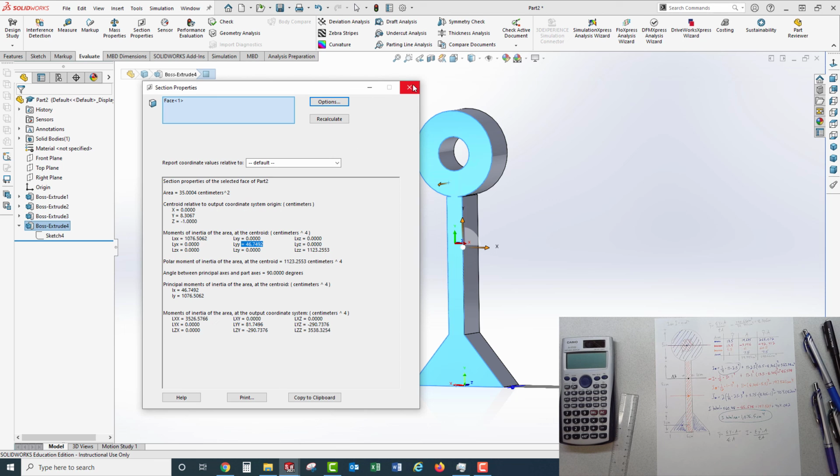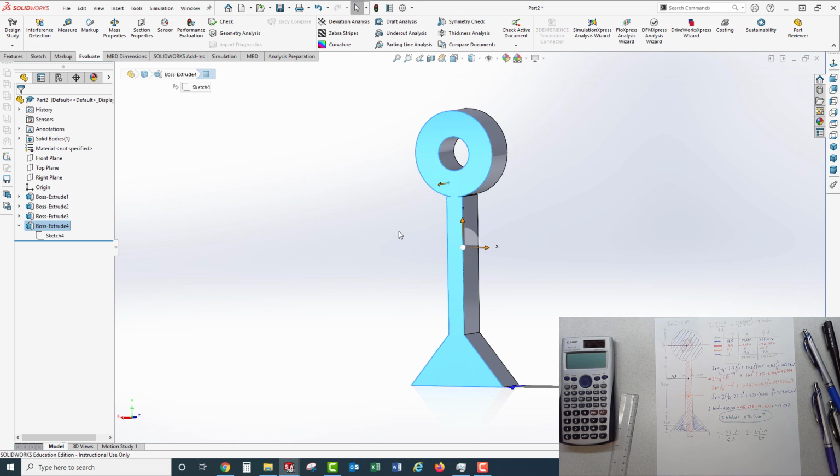Okay, I think that's probably enough about finding moment of inertia of a shape. Remember, general idea, moment of inertia is a representative property of the stiffness of a section about bending. So we can find it by looking at the composite pieces. First step is always to find the centroid of the composite shape. Then once you've found the centroid of the composite shape, you figure out the contribution each shape has to the moment of inertia about that centroid of the composite, of the neutral axis of the whole piece. And you do that using the parallel axis theorem. So, pretty long video looking at moment of inertia, but I hope that helps clarify any confusion you have on how do you find moment of inertia of shapes.